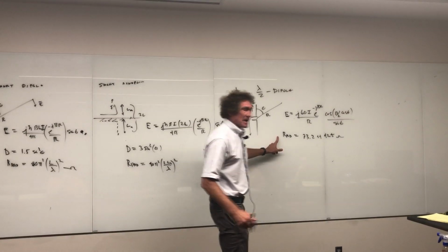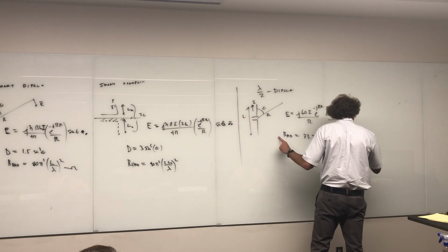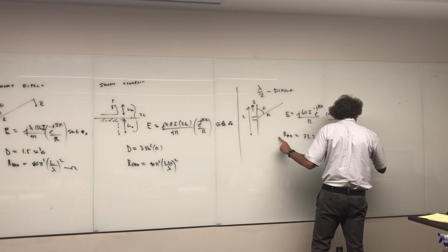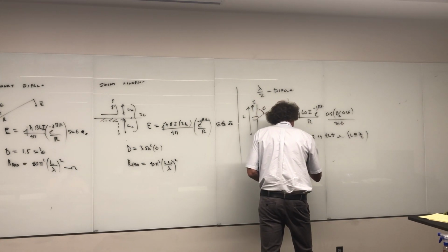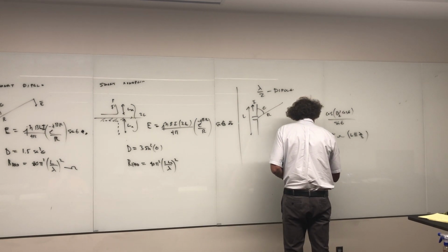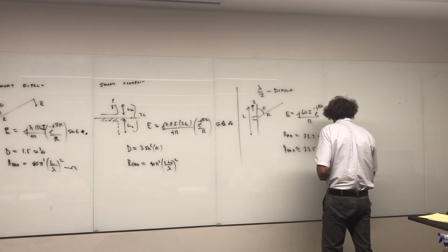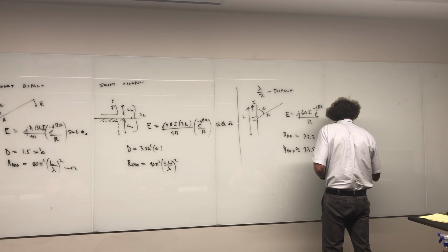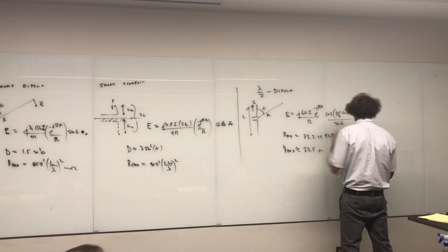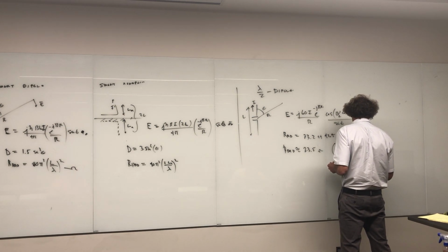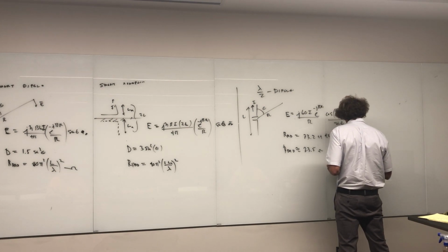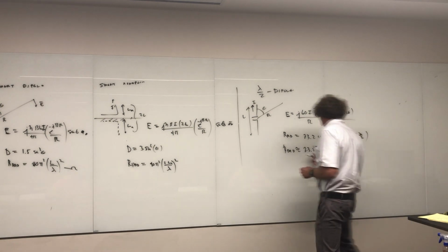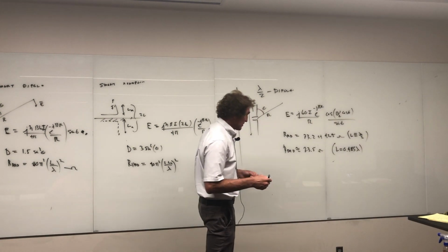Now that is for an exact half-wave dipole. So write this down, put L exactly equal to lambda over 2. Typically, you can also get R rad equal to about 73.2 ohms plus j nothing if L is equal to 0.485 lambda. Then you just get this. You'll have the same exact gain, and I'm about to put that down.